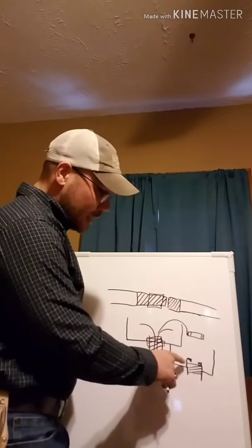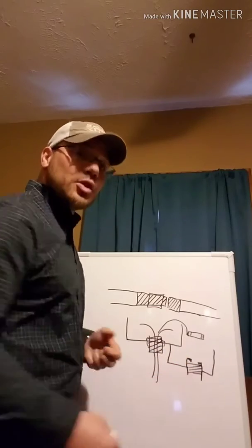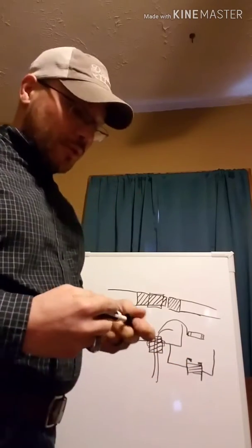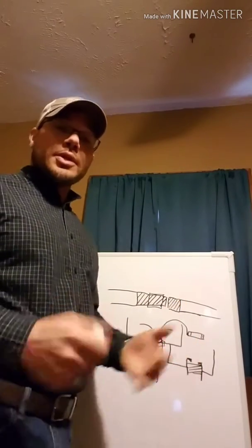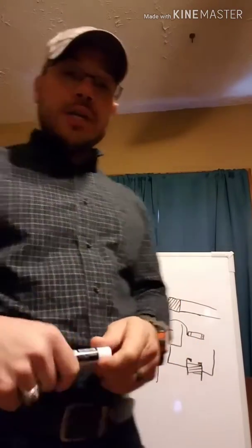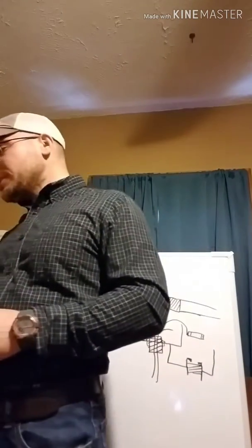If you can see that right here. And so if it has that built into it, then of course we don't have to worry about it. But if it doesn't, we have to put this plastic bushing on it to protect those conductors, right? And again, it's because of cutting and stuff. Okay, almost done here.